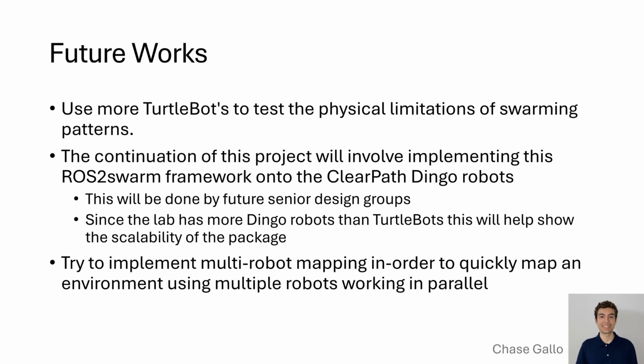It could run on any robot as long as it has the proper sensors and motors, and show its scalability. And in that case with the Dingo, another group would also likely have to use a ROS bridge, because Rasta Swarm is a ROS2 package, but the Dingos run on ROS.